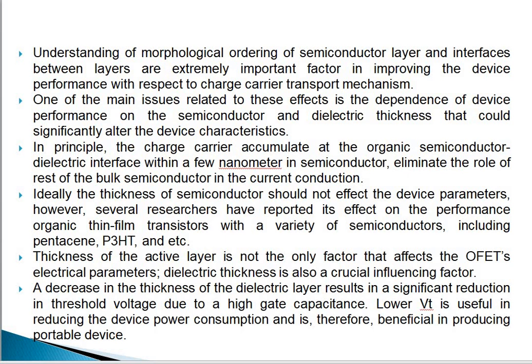In principle, the charge carriers accumulate at the organic semiconductor dielectric interface within a few nanometers in the semiconductor, eliminating the role of the rest of the bulk semiconductor in the current conduction. Next, ideally the thickness of the semiconductor should not affect the device parameters. However, several researchers have reported its effect on the performance of organic thin film transistor with a variety of semiconductors including pentacene, P3HT and etc.